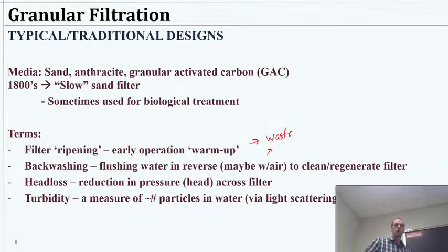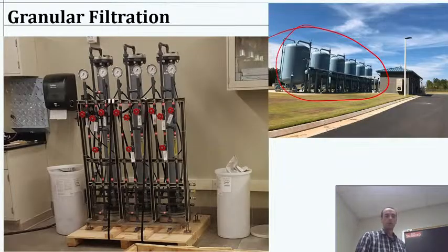And the term we're going to use is filter ripening. If you've ever had a brand new Brita filter or something where you're flushing your water through, for the first few minutes there's going to be these black specks coming out, and it looks messy. Well, that's because when it was made, there's just some smaller debris in there, and they haven't all been caught. Some of it's just loose and ready to flush out. And after operating for some time, you'll be in a more stable, settled sort of situation. More of you can participate with it, but it's kind of neat. You can backwash it. It's just hooked up to the tap water, so we can flow it. We can watch some of the debris coming out if we backwash it. It's not particularly dirty, but it has all those new particles, or the small particles from being a new filtration media.